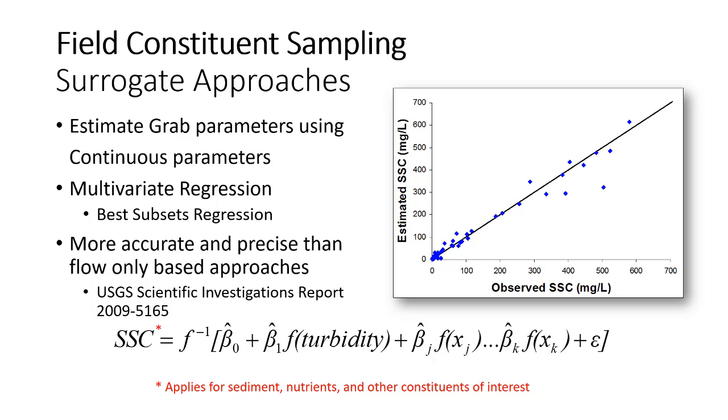So you build a statistical model of all the real time parameters to try to estimate concentrations, and then you compare those to your observed concentrations, which is shown here. It looks like it's a pretty good fit for this particular site. Again, the idea is that we couldn't possibly take enough grab samples to estimate a load, right? We've got to have some way of comparing the grab samples that we're able to take to those high frequency real time measurements that are getting picked up at higher intervals. Does that relationship make sense to everybody? The way that turbidity is related to solids, and why they do that. You guys understand that? Okay, we'll talk a little bit more about that in just a second.